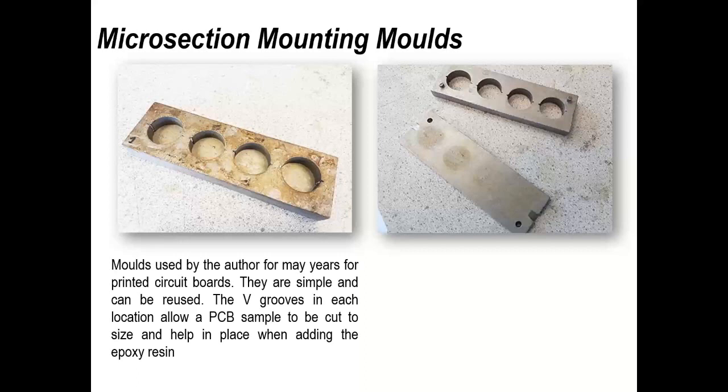So basically you put on a lubricant onto the surface which is compatible, which is basically just a grease, to allow the sections to come out nice and easily when you have allowed the epoxy to cure. You don't want to be bashing them out and possibly damaging the section. You want them to come out nice and easily. But if you forget to lubricate them, quite often they may well be trapped in there, and you have to use a minimum amount of force to force them out.